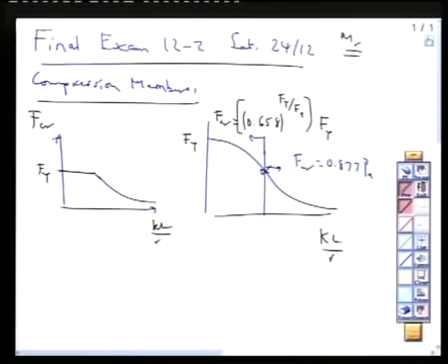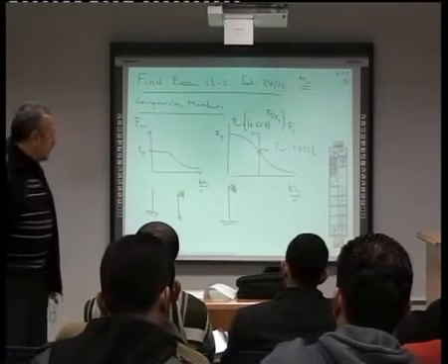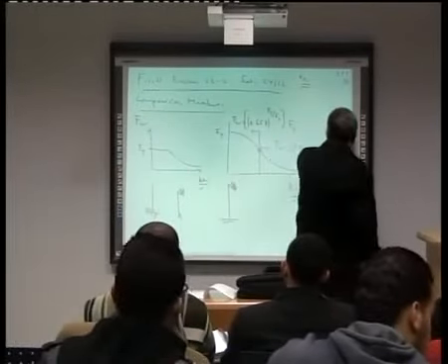What is L? Length of the member or height of the column. What is R? What is K? Effective length factor. Let us remember some types of effective length factor. What is K for this? 2. For this, 1. 0.7 theoretical and 0.8 what? Practical. What about frames? How do you find K factor in frames?